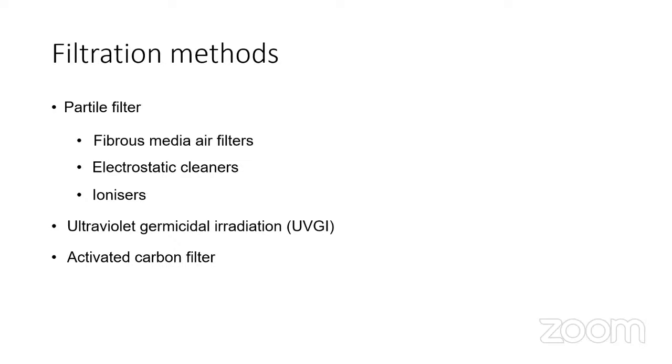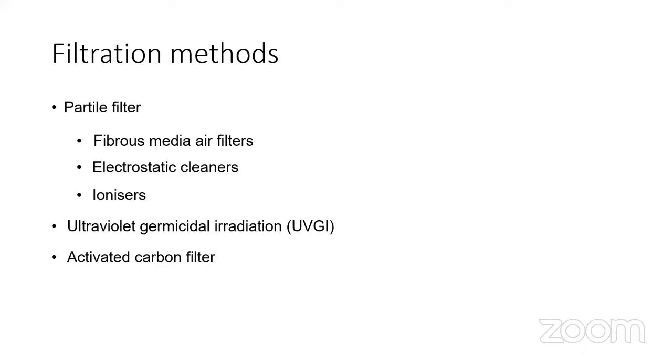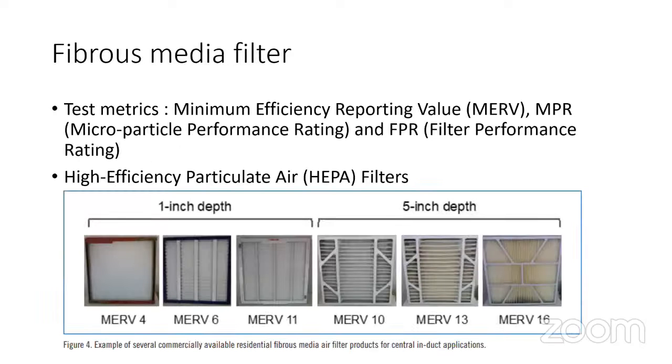And only sorbent media filters are normally used for gas phase cleaning for gaseous pollutants, without producing any harmful byproducts. Normally they have a finite capacity for adsorption, so there is a need to replace them regularly. The adsorption process refers to individual molecules, atoms or ions gathering on surfaces. An example would be water vapor getting adsorbed by silica gel. So these are the filtration methods. We'll discuss further on them.